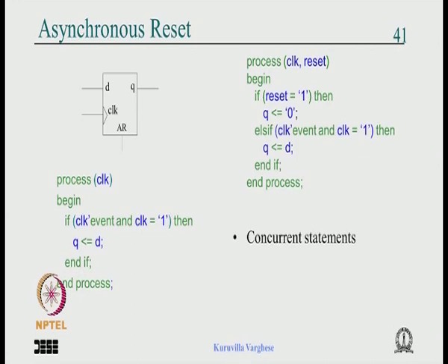So can we have a concurrent statement for a flip flop with asynchronous reset? Yes, we can use when-else, which is equivalent to if-then. We say Q gets 0 when reset is 1, else Q gets D when clock'event and clock is equal to 1.